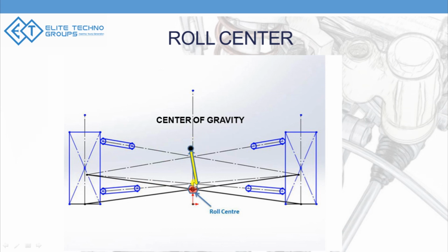If you reduce this distance, your movement will also be minimized, because this movement is nothing but r times theta. So the linear movement of your body will be reduced, and in most F1 cars they have this distance much closer together.